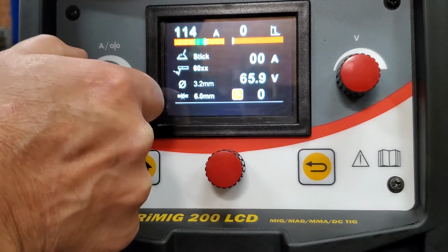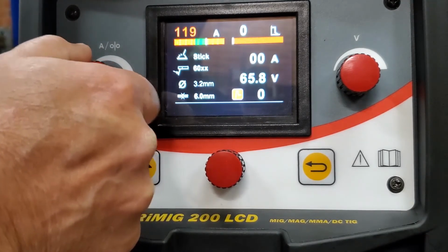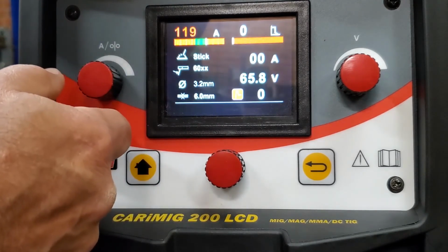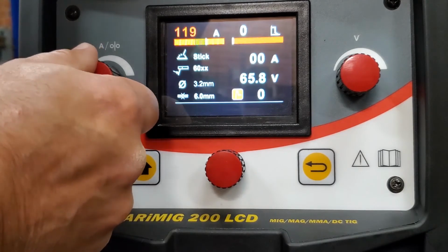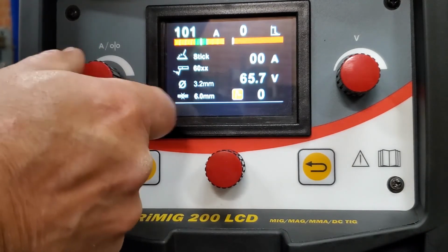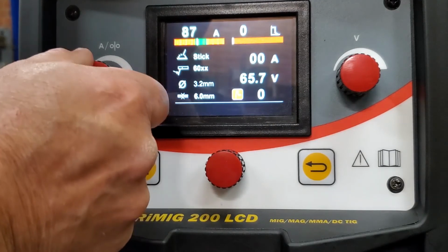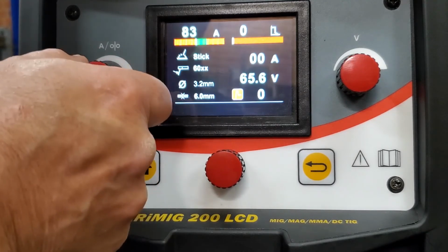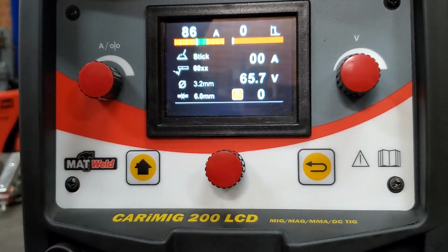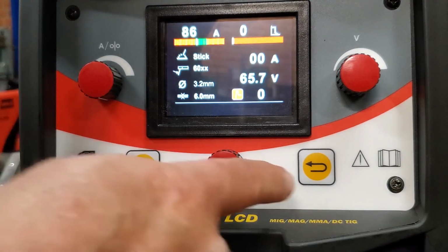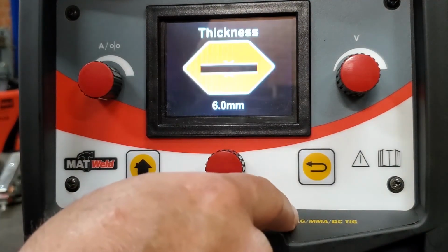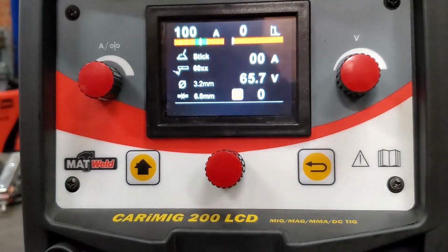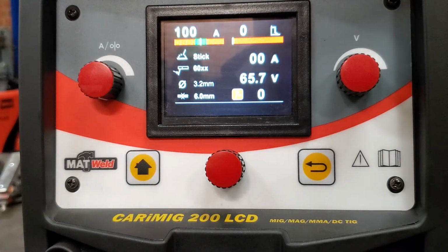It allows you to adjust. It also will flag. In this case, if you go a little bit over on the top side, it flags red. It will still weld, but it's the wrong setting. The same at the bottom end, it'll also flag. Now, if you don't like the settings that you've changed and you want the standard factory setting, you just press one step back, enter again, and it goes back to the 100 amps. That is as simple as it is to set up or adjust your machine.